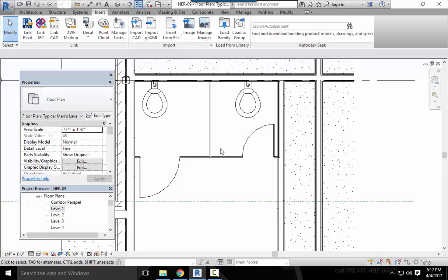With the toilets and stalls in place, you need to add a grab bar to the accessible stall. Again, Revit doesn't provide this content. You'll need to either make this component yourself, which is covered in bonus chapter 2, Creating Families, or use one from the book files that you downloaded with the bathroom stall. To add a grab bar, follow these steps. Zoom into the accessible stall as shown in figure 9.39.